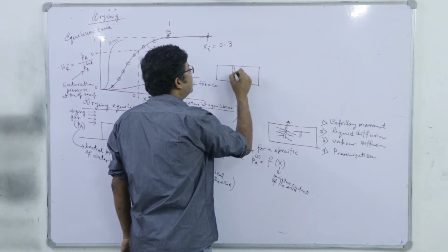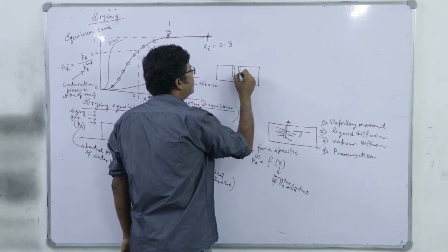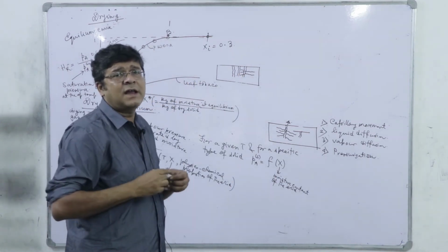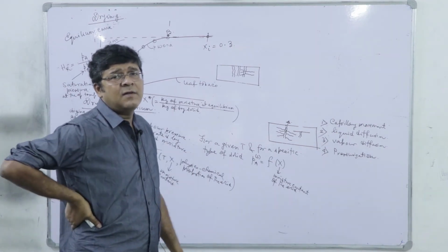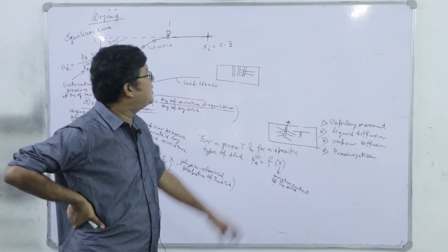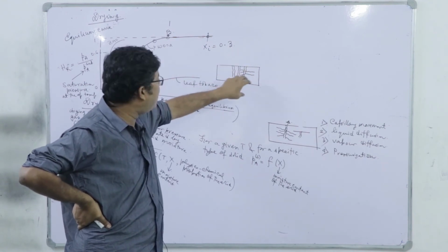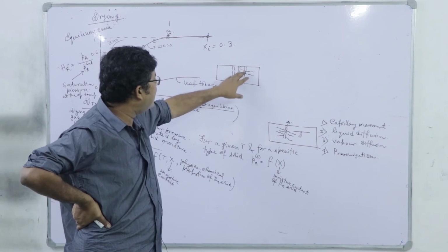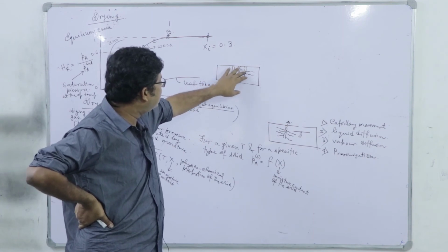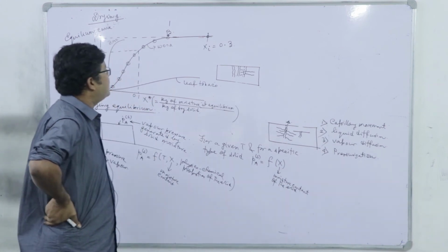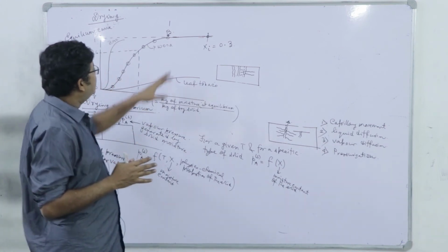next, it releases moisture from the capillaries, and the macro capillaries are being supplied by micro cracks and micro capillaries. So, micro cracks and micro capillaries may have a dimension in the order of nanometer, where these intermolecular forces are quite prominent, and even in macro capillary size there are intermolecular forces close to the wall, right. So, as a consequence, what we can say is that here